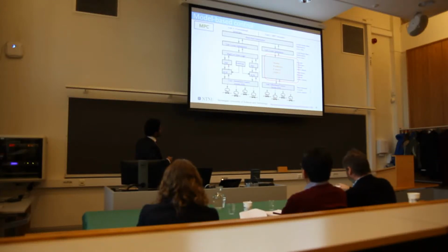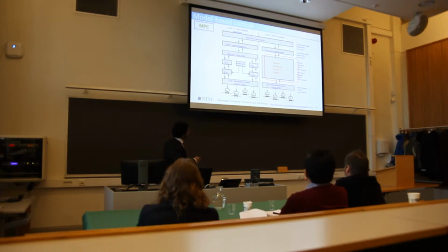In comparison to traditional control, it will replace a lot of PID loops. So if you read here, it's a global steady state optimizer at the top, then you have a local steady state optimizer, then you have dynamic optimization through MPC, using your decision variables in the best possible way dynamically to achieve some dynamic objectives, and then you have lower level PIDs doing the work instructed by MPC.